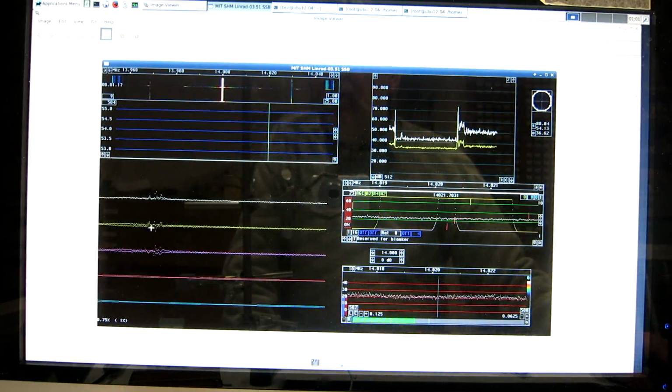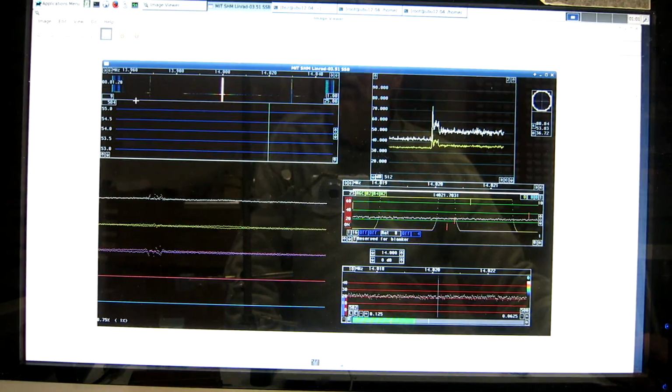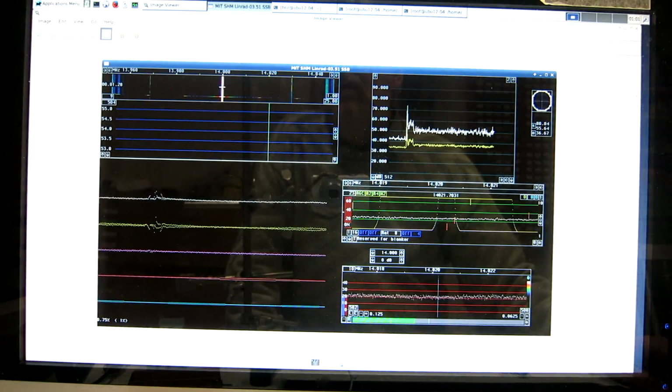Looking here, you see there are some errors. There is a signal on the Nyquist frequency. We can see it here and here. And there is also some error near the center, which you can see as a curvature like that, up or down, both before and after the pulse.